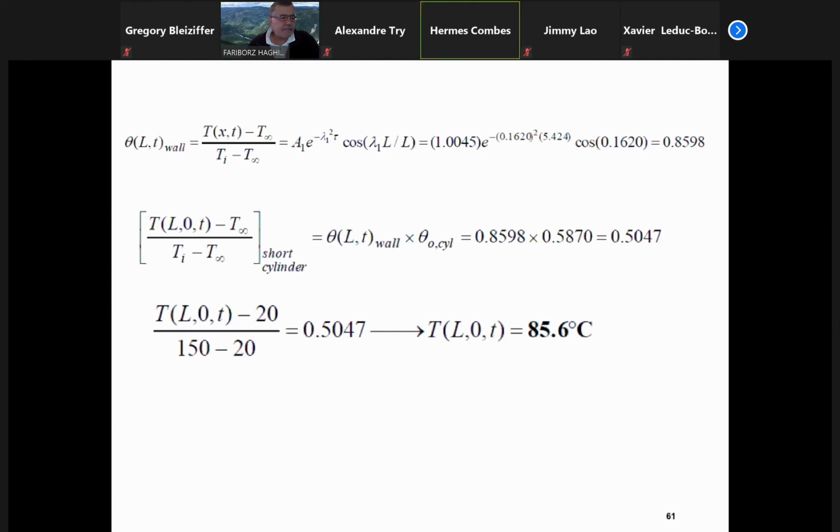We could have used the simplified equation, because that shows the temperature at the center is almost the same as the temperature of the surface. It means the internal resistance you were able to ignore. Very good. Therefore, now we have an analytical solution and we have a graph to consider the variation of the temperature in a solid material as a function of time.